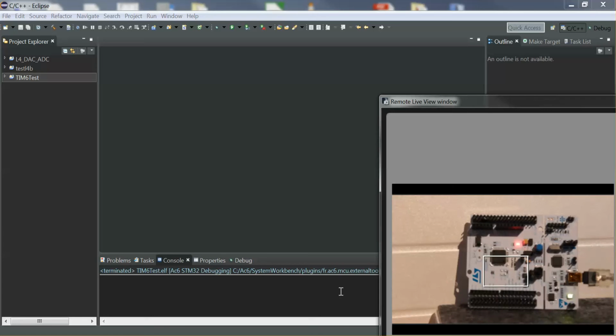So basically, the other problem that was there when I used Eclipse and CubeMX is that I had to physically copy the project from Cube to Eclipse, and I used a Python script for that. But obviously that means that if you create a project with Cube, then you add your code and then you copy again the project from Cube, you will overwrite the code that you created. So there is a much better way, and this is what I'm going to show you today.